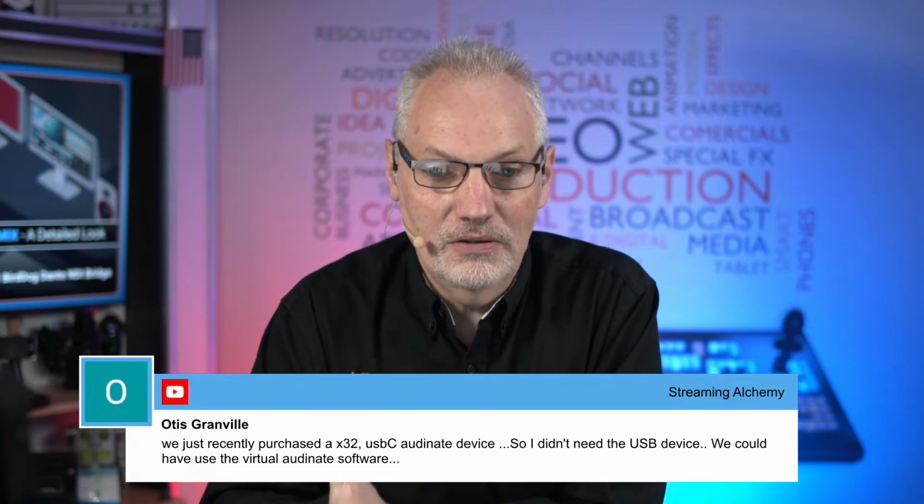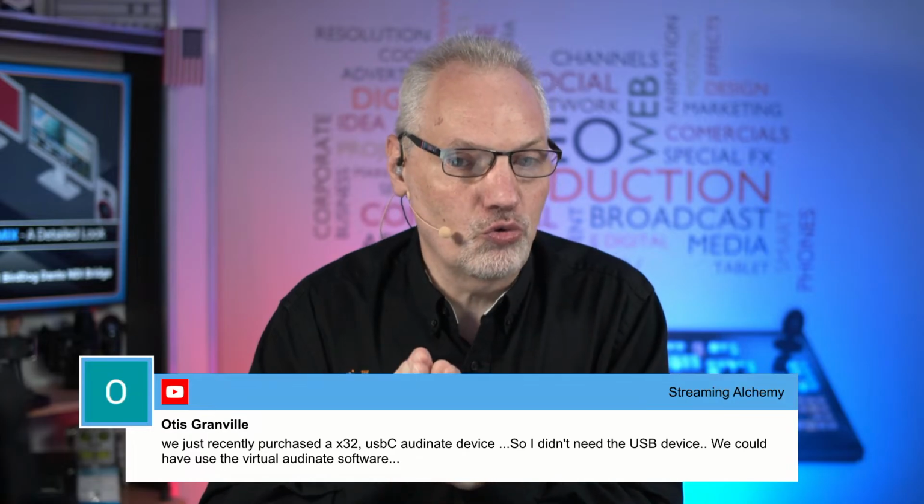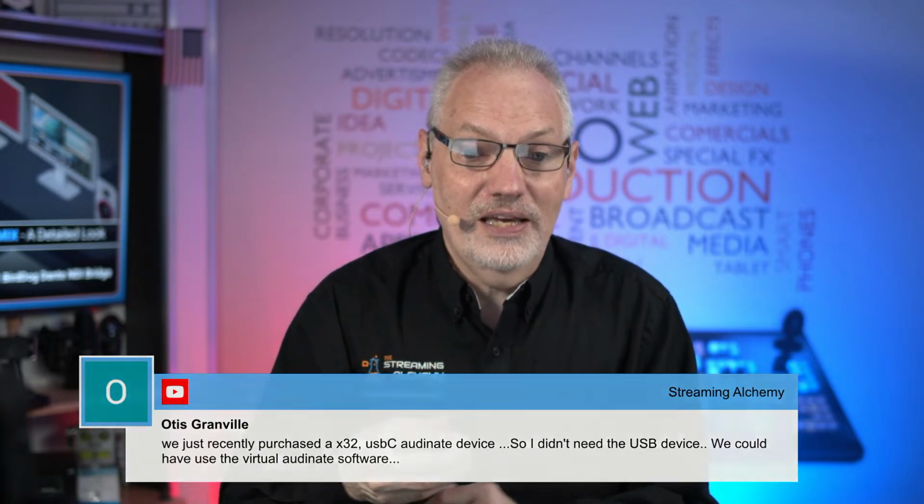Dante as a protocol is not a mixer, it's a router, and that's very, very important. So for instance, using Dante and everything we set up with Dante Controller here, you couldn't actually do something like a mix minus, because I can't say I want to send these 3 sources to this one input. You don't have that ability. It's not mixing, but it will give you that type of routing, which can be very important there. So just keep that in mind.